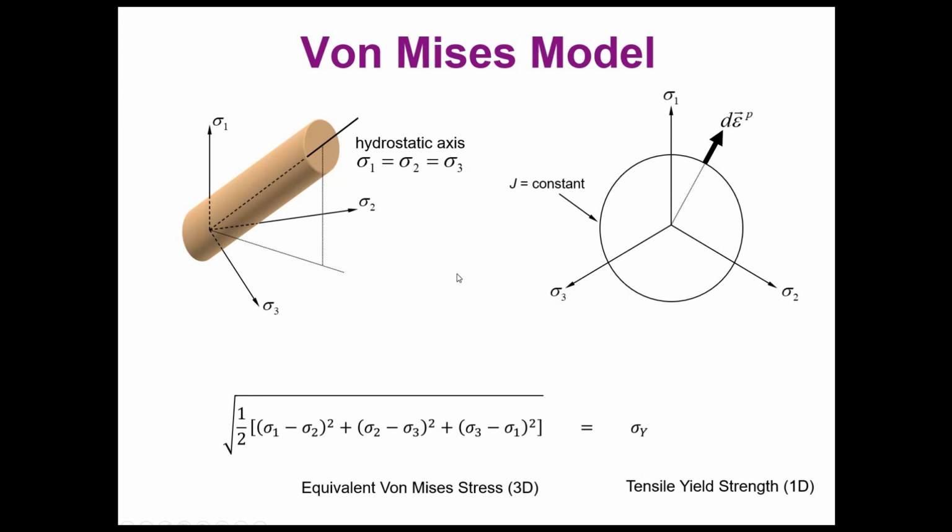And this is the reason why a very simple way of analyzing your results is when you see the levels of the equivalent von Mises stresses and you compare with the yield strength, the elastic yield strength, because it's a property of your material, you have an idea of how good or how bad you are in terms of the state of the stresses in your structure or soils.